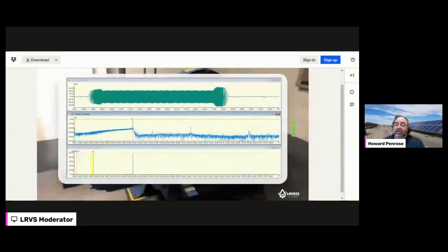So this is how long it takes to go from the first floor to the 11th floor. That's the flat spot in between. The large bulges at either side are the machine, the elevator basically standing still and then accelerating, then going at a constant speed from the first floor to the 11th floor, and then decelerating and being held in place before the brake closes.